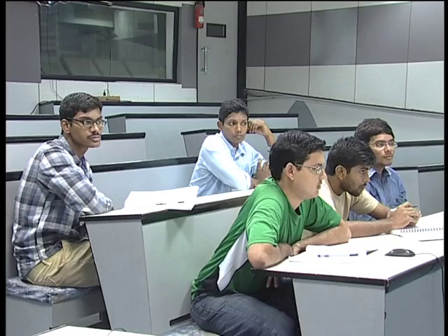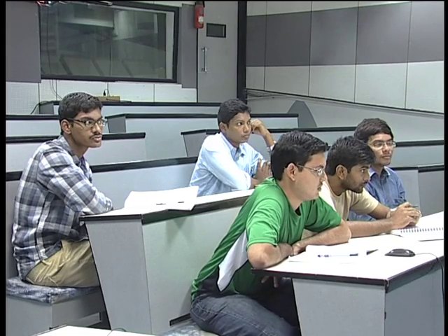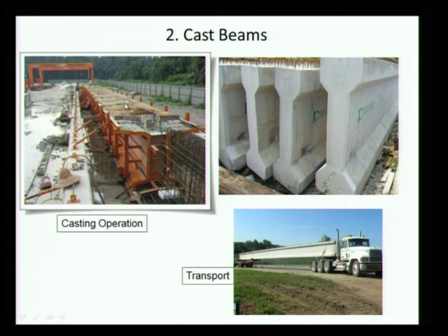If I have enough crew, I can fabricate reinforcement for all 6 at the same time. Reinforcement fabrication would ideally mean that you fabricate in the yard and then place it where you're going to pour the concrete? That's exactly what it means. I'm not fabricating the reinforcement on the bed. I'm fabricating it outside, so the bed is free, and then bringing it and placing it in the bed, doing whatever tying is required, and then doing the formwork around it.